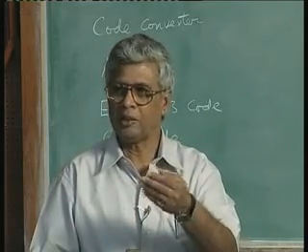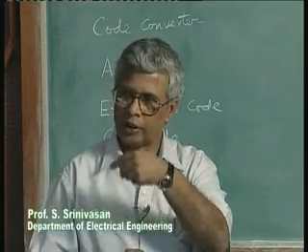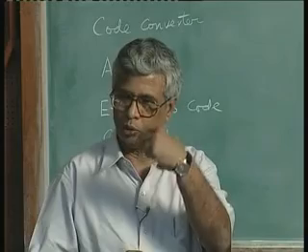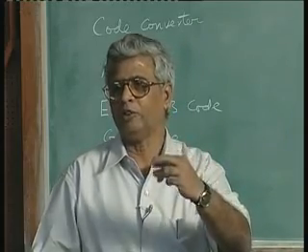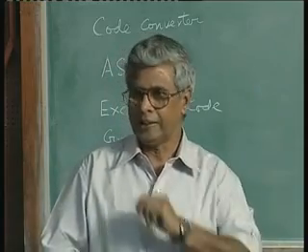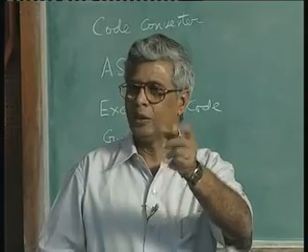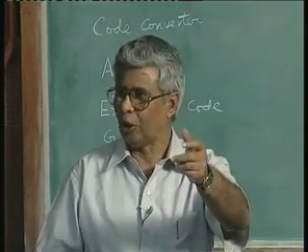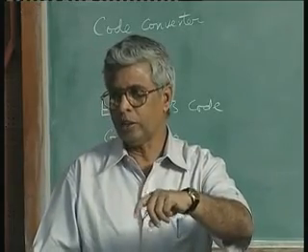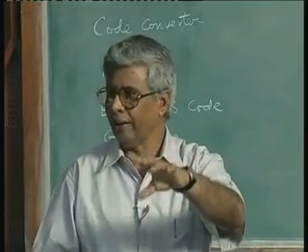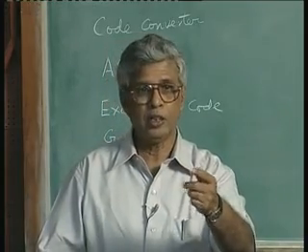Now all the 4 binary digits have to be changed from the previous values. First one has to become 0, second one has to become 0, third one has to become 0, fourth 0 has to become 1. This is called switching. Changing of the value of the binary digit from one value to the other is switching. Why did I say it's switching? Because we represented binary operation by a switch. A closed switch is a 1 and an open switch is 0. So a switch has to be opened to make a 1 a 0, and closed to make a 0 into a 1. So 4 switches have to be operated when I want to change a number from 7 to 8.